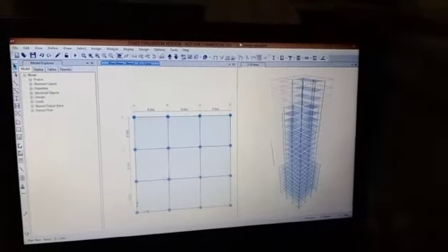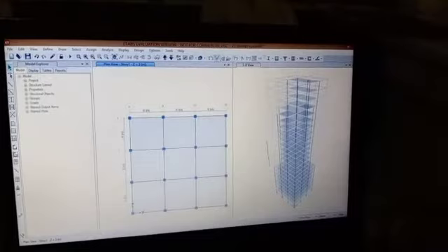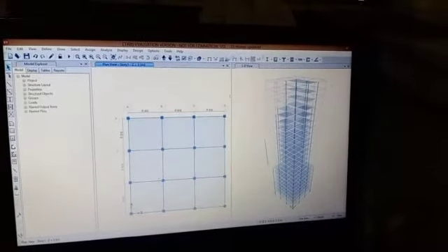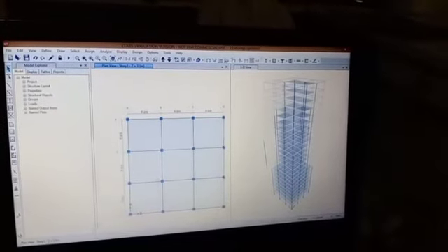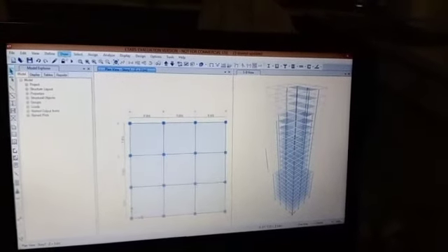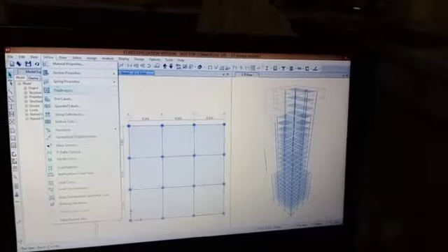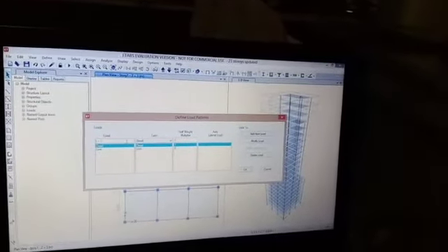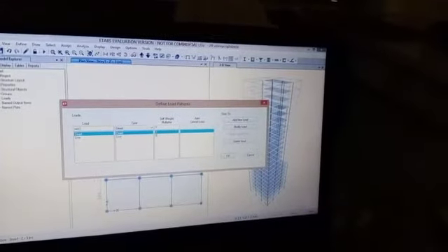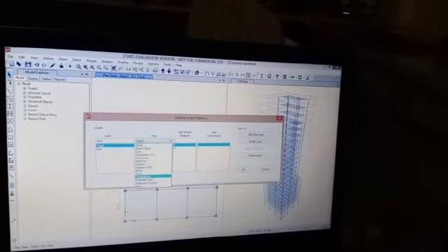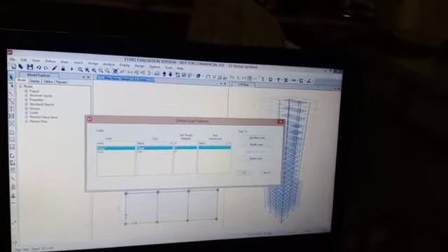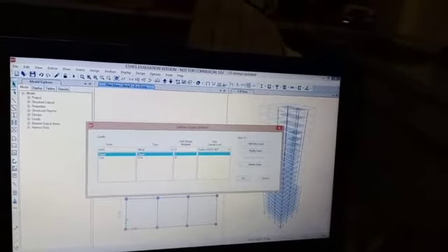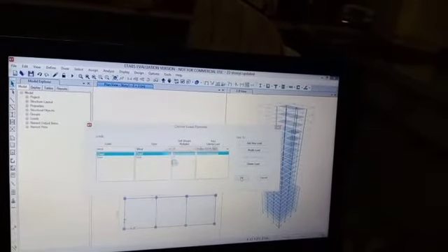Now we have to apply the wind loads for the different sections of the building, which is varying at different structures. And now we have to first define the wind load. Go to define section and then load patterns, and then type wind load, wind, and select the type as wind, and then autolateral load as Indian IS 875 1987, and then click on OK.